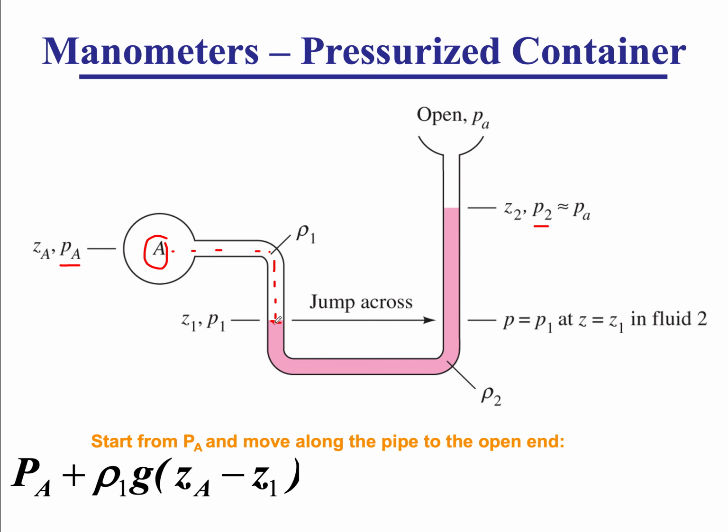And if I move within the fluid and get to the exact same height, it's the same fluid, I don't have any solid obstruction, I don't have a pump or anything, it's still static fluid, completely free and open, then I would not expect any change in pressure at a constant level of fluid. So that's still the same P1 over here. So I've already walked through the fluid until I got here, that's P1, and that's what's drawn right over here.